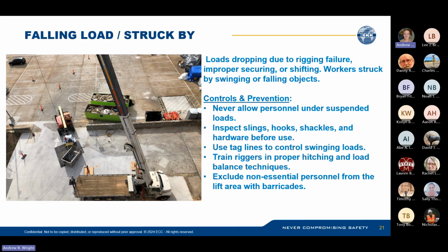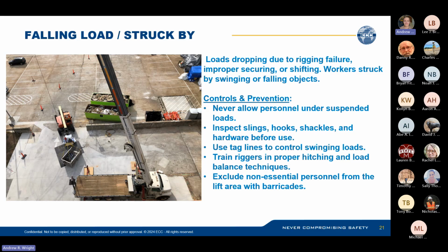Exclude non-essential personnel from the lift area with barricades and signage. So typically, if you're going to set up a crane area, I always have a very healthy buffer zone around your area with plenty of warning signs and flagging just to keep people out of that area that are not vital to the lift operation.